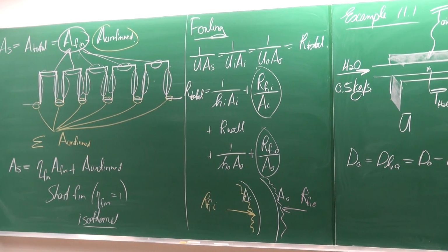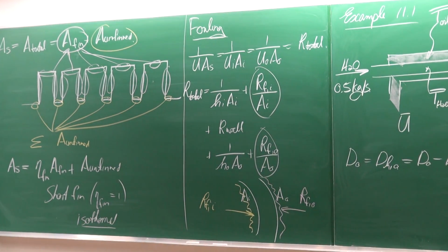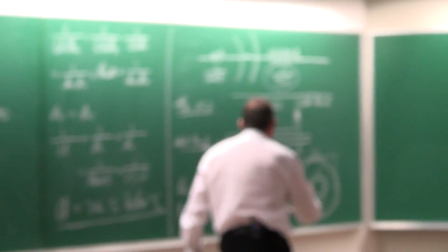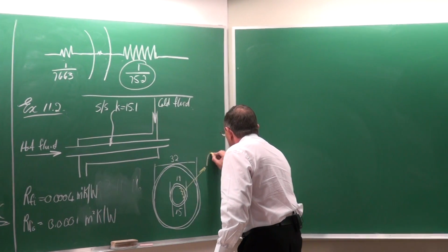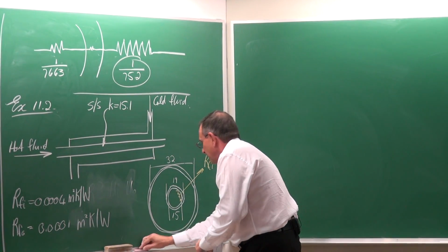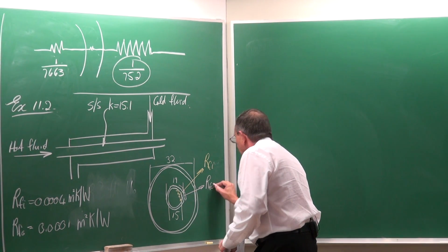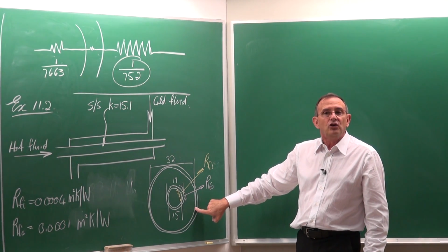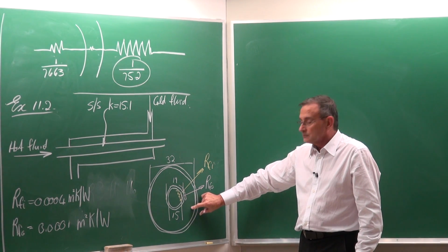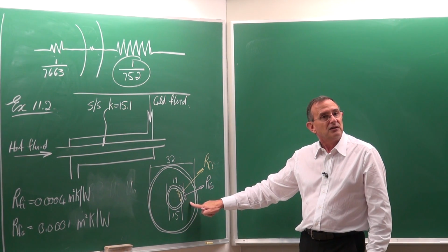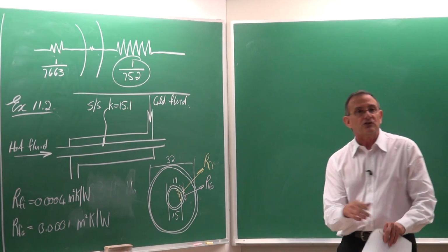In this case, the only fouling that plays a role is the fouling on the inside, RFI, and the fouling on the outside, RFO. Fouling doesn't really play a role in the annulus because there's no heat transfer there. Obviously, if there's lots of fouling, it will influence the velocity. The average velocity would actually increase and the pressure drop will increase.